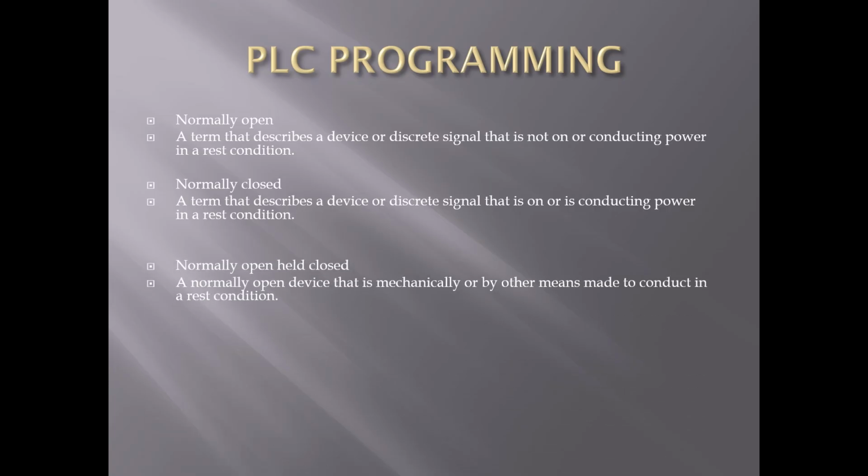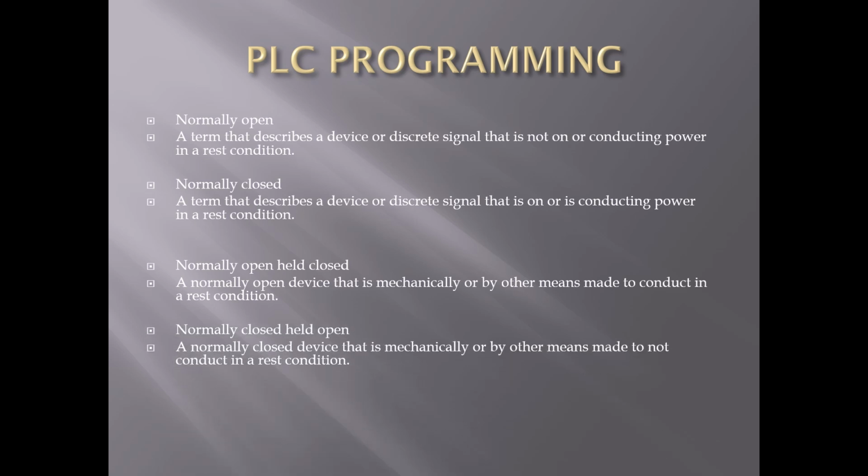Normally open, held closed. A normally open device that is mechanically or by other means made to conduct in a rest condition. Normally closed, held open. A normally closed device that is mechanically or by other means made to not conduct in a rest condition. A one-shot signal. A one-shot is a signal that exists for one scan of the PLC program.